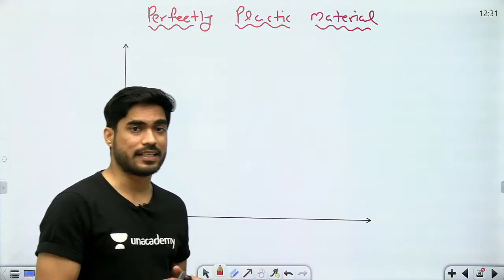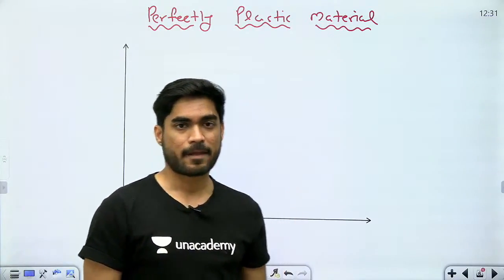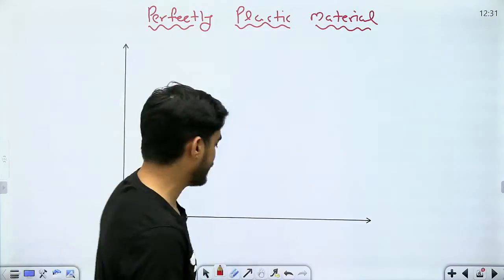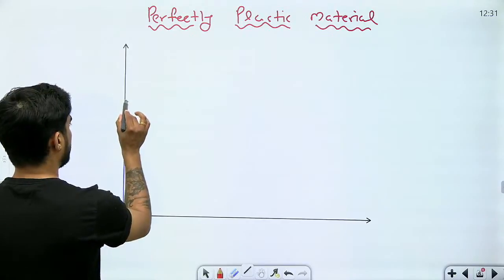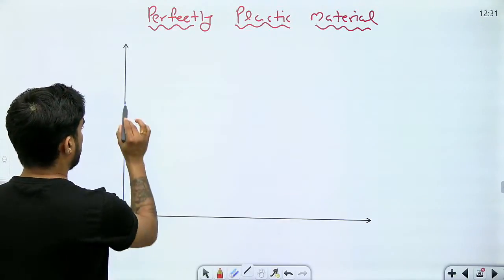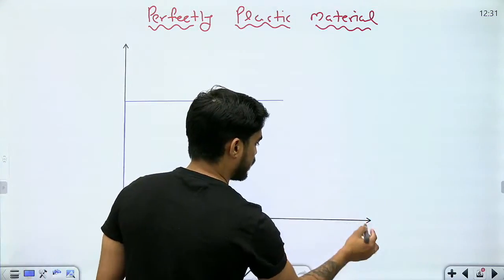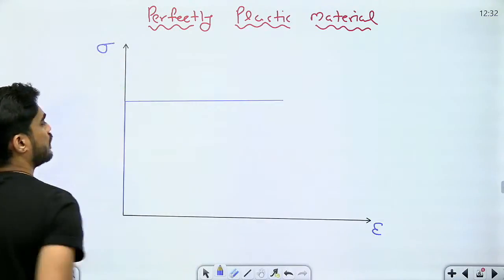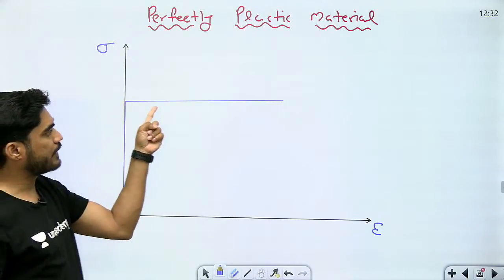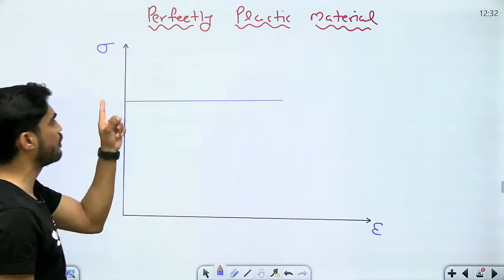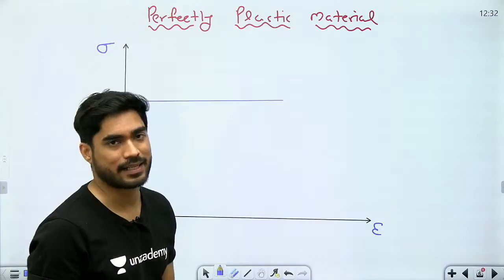During plastic deformation there is increase in strain at almost constant stress. So a perfectly plastic material will be one in which up to yield point there will be no deformation. Yield point तक कोई strain नहीं रहेगा, and after yield point we will have deformation at constant stress. After yielding हमारे पास constant stress पे deformation आएगा. So this will be a perfectly plastic behavior. इसको हम rigid plastic, perfectly plastic भी बोलते हैं. This is also called rigid perfectly plastic material. Okay.